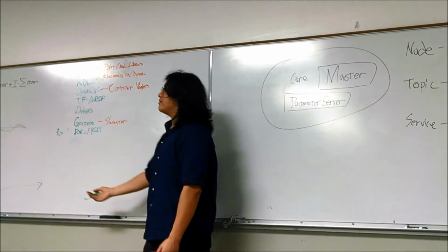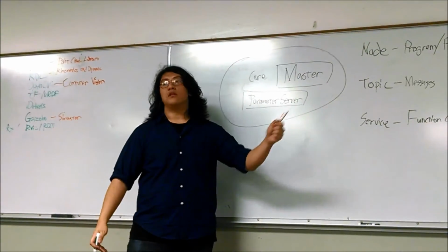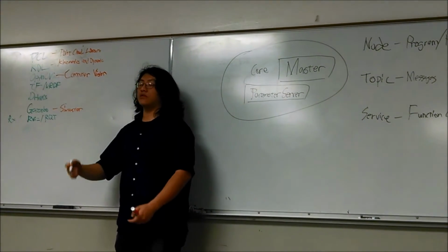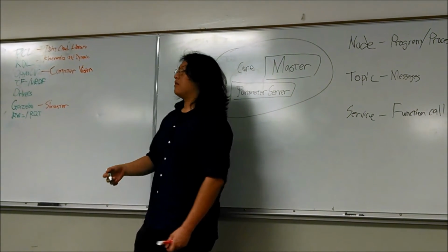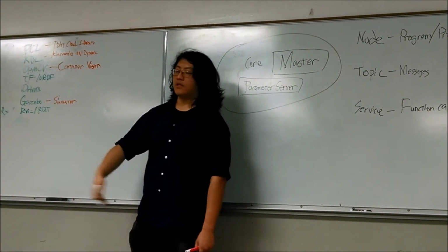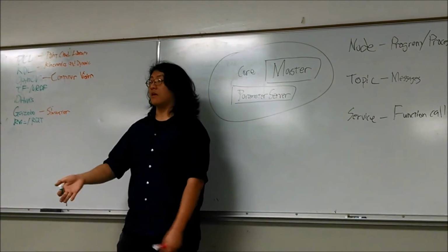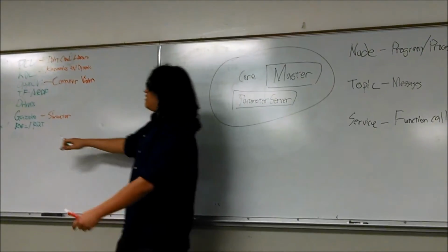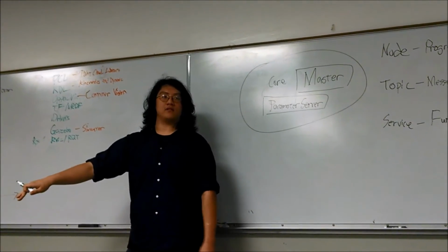It has access to the console. When you write ROS nodes, the convention is that instead of using something like printf, you use ROS log. You use ROS's logging system, and that will go to a console. If you publish any kind of errors, you get to view them in a console that's basically the same as when you're debugging code, you compile, and then you have your compile errors. You look at it in that format. That's the console. What's the third one in RQT?